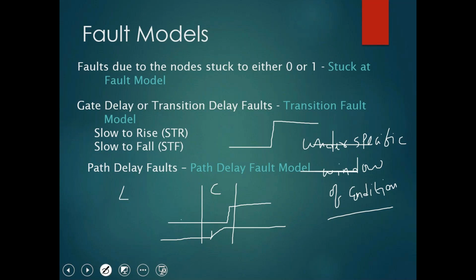It may not impact the driving circuit logically, but in terms of delay it affects. So my capture window is only this, which means I have only one capture window like this. Within this duration of the window, the delay of the data should also be accumulated, and it should come within the proper time.